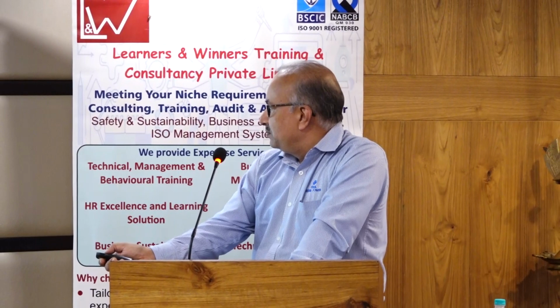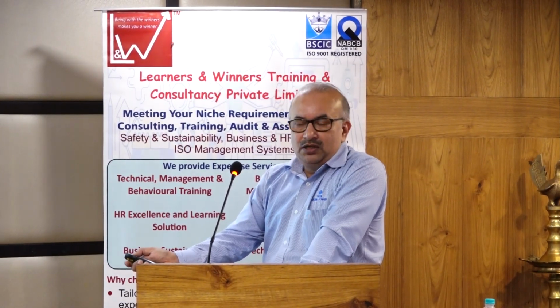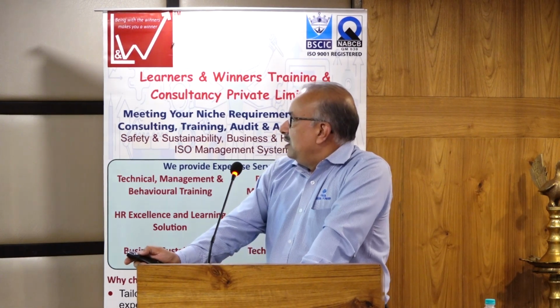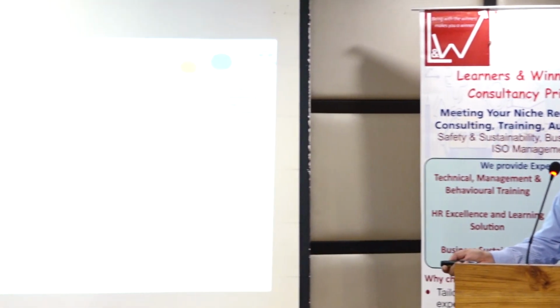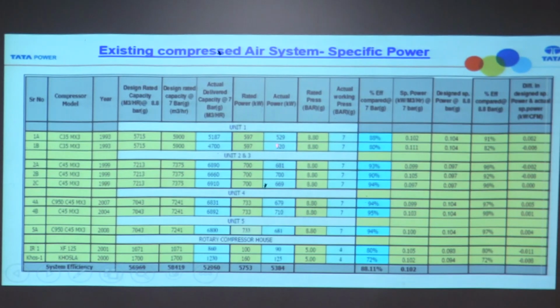These are the flows, and you can see the difference between the instrument air flow and service air. This is the specific power consumption. These are the actual delivered capacity against the installed capacity, and this is the required power, and this is the actual power.